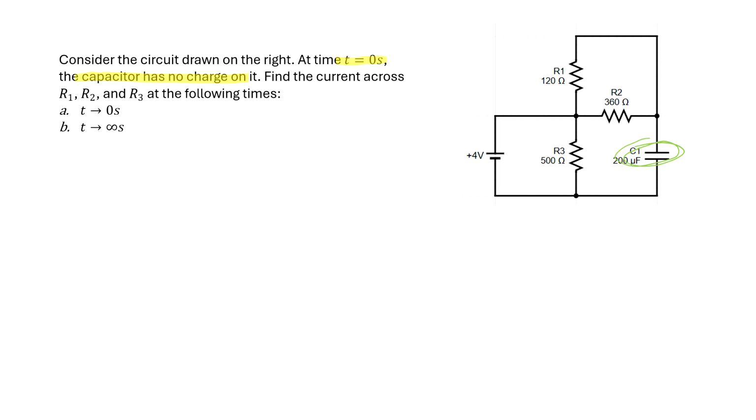Let's look at this picture and let's really try and understand what it is we're looking at, specifically by drawing some loops, right? So Loop's law is all about going up some elevators and down some stairs here. If we go up this 4-volt elevator, the loop law says that by the time we get back to the bottom of the battery, we should go down by 4 volts. If we take this pathway here through R3, well, notice actually we're already back at the battery. We didn't have to go anywhere else, and we're already here at this 4-volt battery.